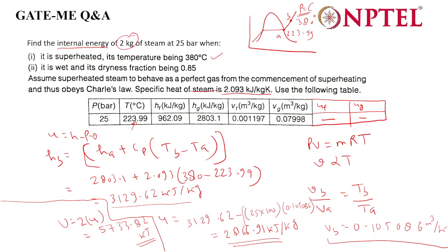Sorry, I think we need to use CV. No, CV also you can use now? How will you say CV for constant pressure? Where do you use CV? We can find it with CP only, and you have to use enthalpy here. If it said a closed piston cylinder system, then you go like that, but it is not said here. So enthalpy is the way to go.